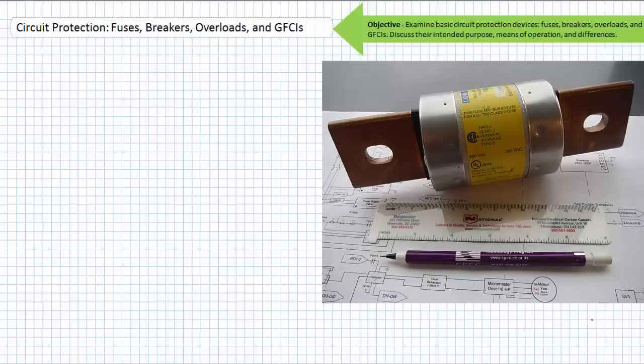Sometimes it's not that easy, because often the metal alloy element is covered with an opaque body covered with a filler. The filler, often quartz sand, is used to dissipate the heat in the fuse below the rated current, and in the event of excess current, the sand is there to quench the arc that may form between the two terminals. Here's a big old bladed fuse.